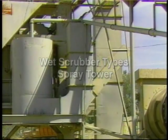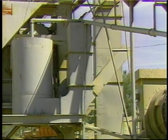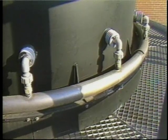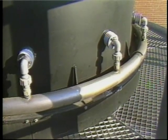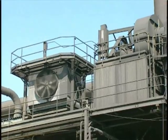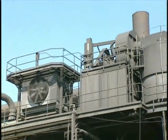The spray tower is a low-energy device and is the simplest wet scrubber used for particle collection. It consists of an open vessel with one or more sets of spray nozzles to distribute the scrubbing liquid. Typically, the gas stream enters at the bottom and passes upward through the sprays. The particles are collected when they impact the droplets. This is referred to as countercurrent operation.